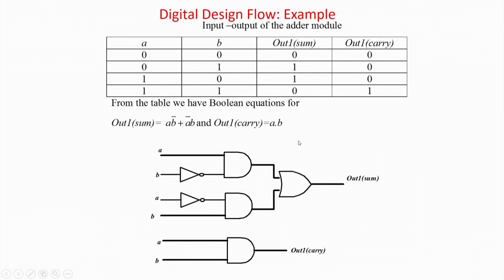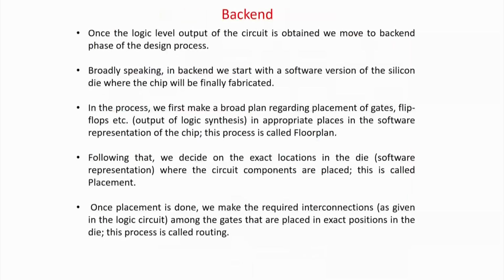So this is the example of a gate level synthesis. So the simple adder, as you know that this is A, B, full carry, you just require a Karnaugh map to get the circuit as the output. But if it is very large, Karnaugh map and Quine-McCluskey will not be able to do it. You have to use some heuristics called, as I told you, espresso.